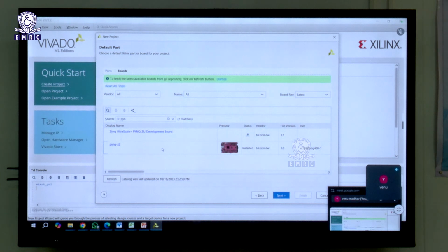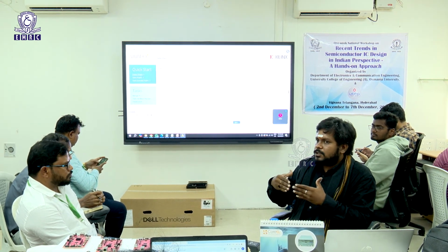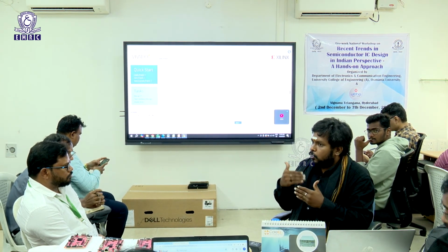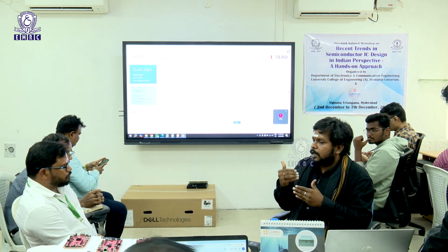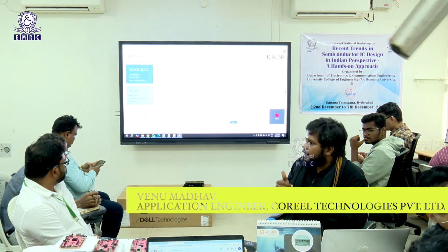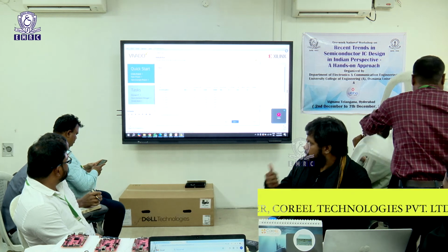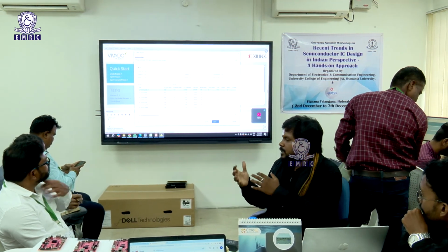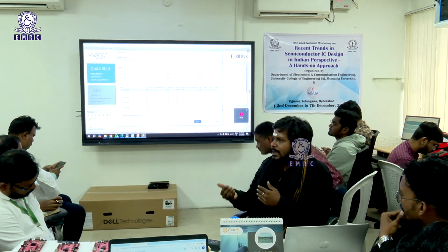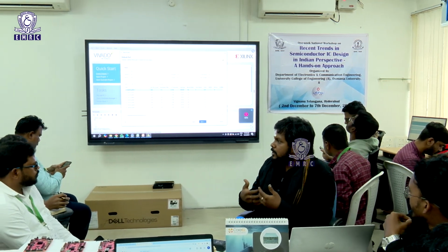Then there is the speed grade. -3, -2, -1 is going to be the speed grade. You have a particular design, right? Once you start with a design, you will have an understanding of your requirement when it comes to resources. How many LUTs do I need? What kind of IO pins do I need? Do I need some kind of sensors? All such information is available to you. So based on that, you can decide on what FPGA you are looking for.